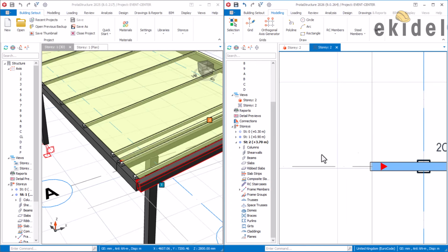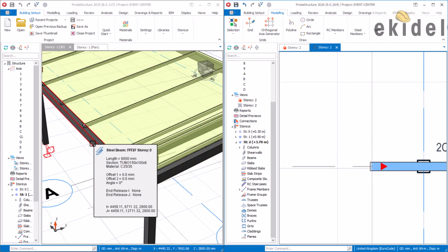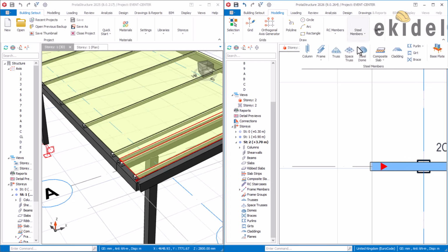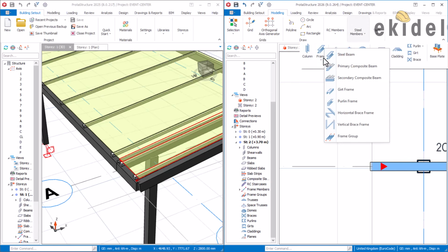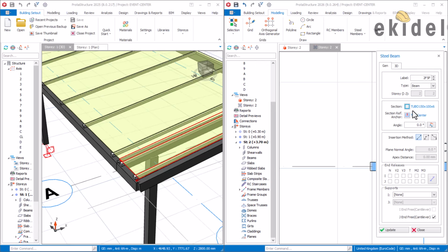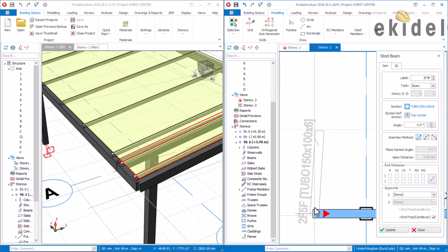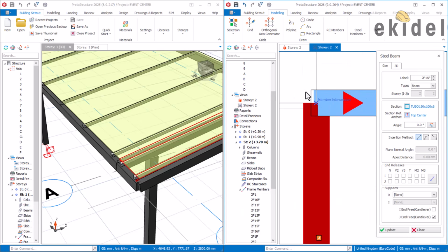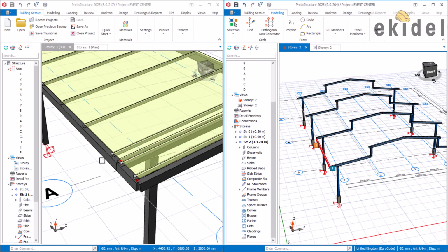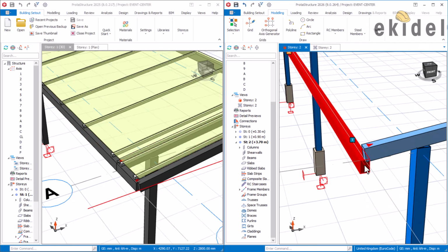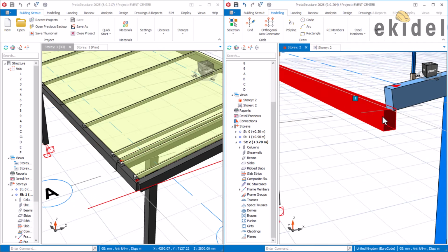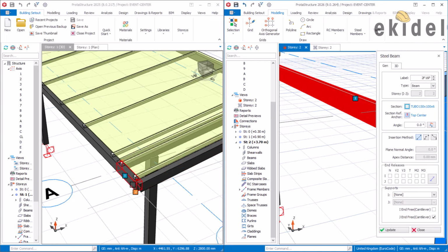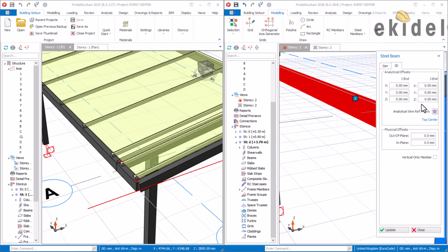And what is this beam section? This beam section is still the same section, 150 by 100 by 6. Come again here, click here, sorry, not the column, click here, then beam, and make sure you are on that section, 150 by 100 by 6. Then come here now, click on this first one. Insert the first one, which is from here to here. Now don't continue yet until you have made it align. So coming here, I can see what we have here. This is showing below, which is not nice. I'll click on this now, open property of it, meant to flush like this. Then come here, click on this here, and then choose here that says bottom center.